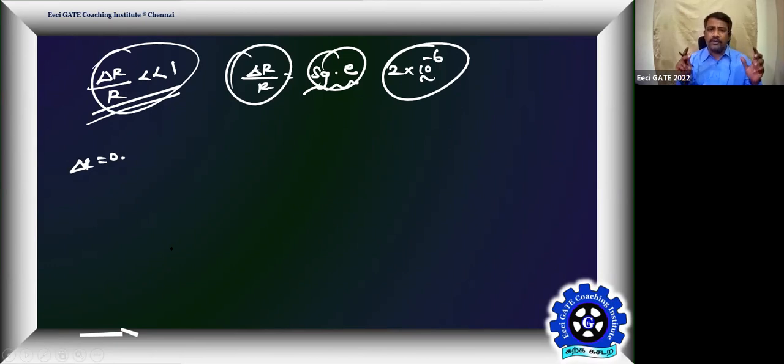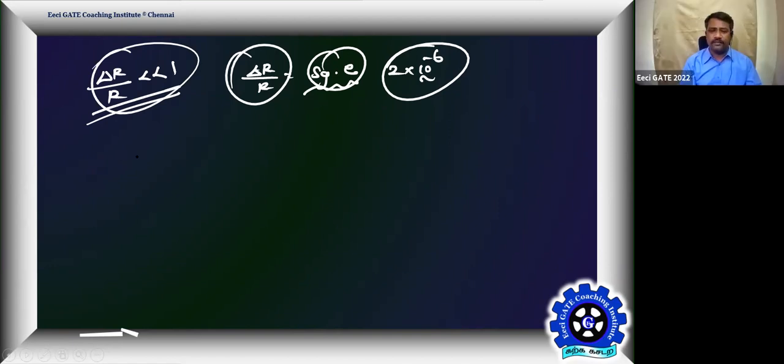Okay, I'm talking about two sensing elements. One is a load cell. It is responsible to convert the force into strain, and the strain gauge is pasted on the strain surface offered by the load cell, and it is simply sensing the strain, converting that into change in resistance. So one is a primary sensor, that is a load cell, and another one is a secondary sensor, that is our strain gauge. Clear? All of you getting this point? Is he right? Yes, sir.